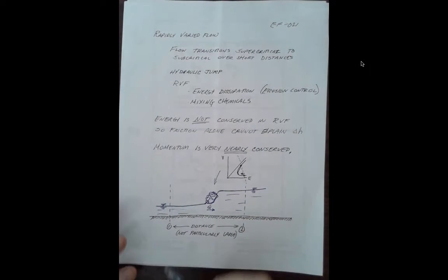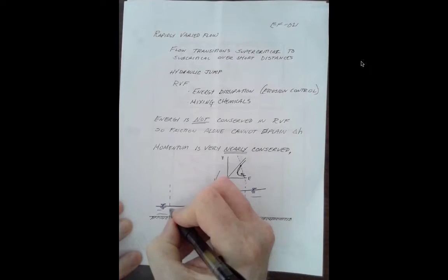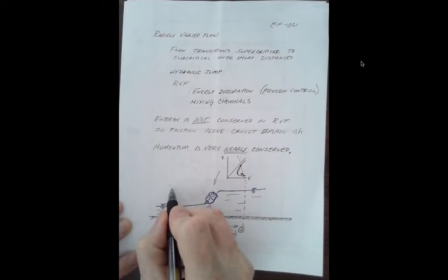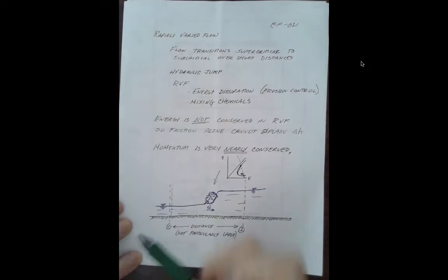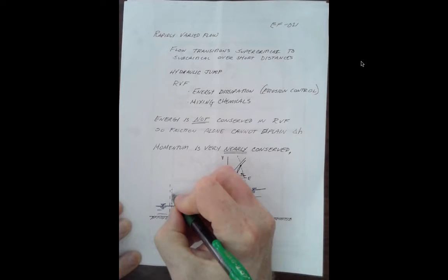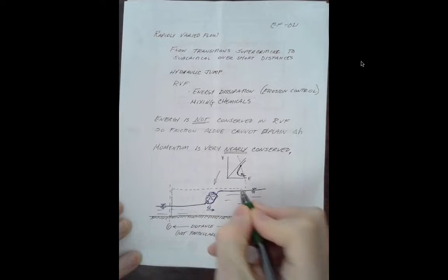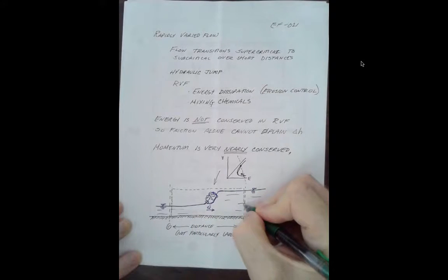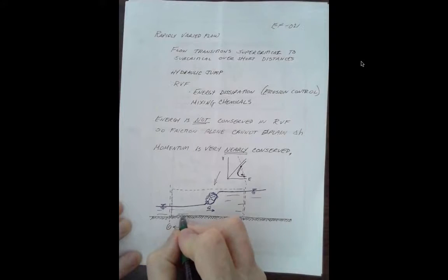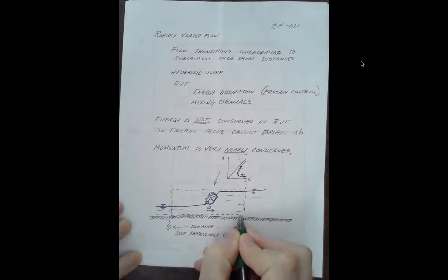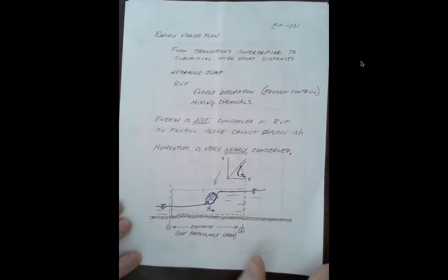The tool for analyzing hydraulic jump is, of course, implied as a momentum balance. So let's go ahead and produce our control volume. Well, I'll go ahead and stick with my favorite control volume color, which is green. So there's my control volume. It's supposed to just include the hydraulic jump. And if I was really anal, I would make the control volume follow that path, but I'm not that anal. So let's pull our control volume out and take a look at it.